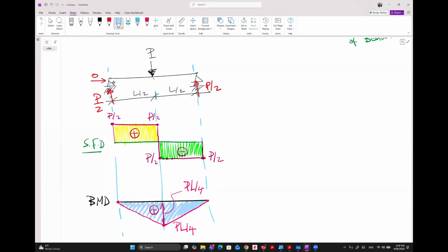Do you have any question, guys, for this one? Under the bending moments, if we have a curve, that means we don't have any force in any part of the beam besides the left and the right. Is that right or no? For a curve instead of a straight line. Yeah, all the time, if you have a point load, the moment lines will be straight lines.